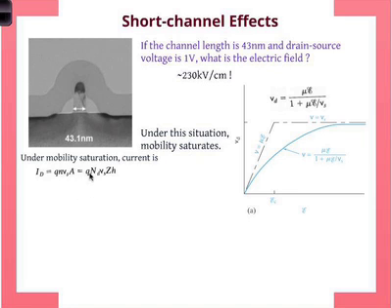It's pretty straightforward. You plug the numbers in. q is the same. n is just Nd, the doping concentration, since it's N-type material. Area is Z times H. Z, remember, was the width, the depth of the channel coming out of the plane, and H is the height of the channel. If you recall the picture we had before, and you plug those in, you get an expression like that, and that's a constant. So now that's your saturation velocity current, which is different from what we saw before.